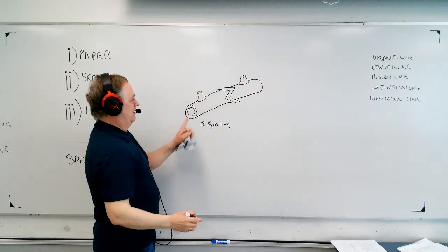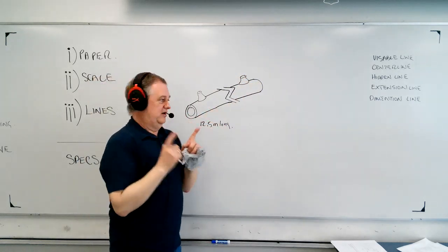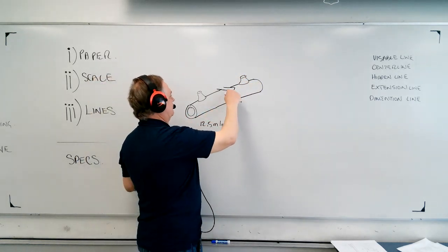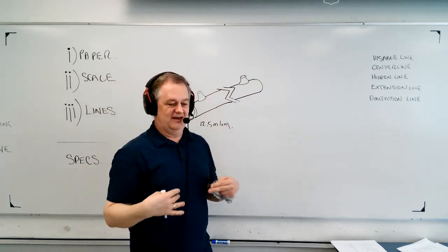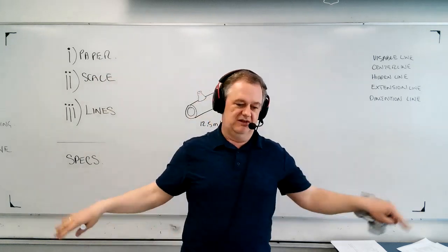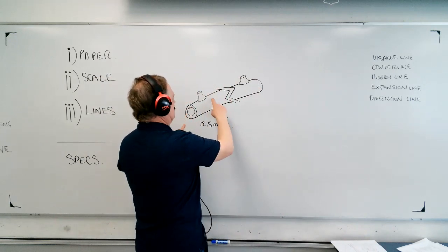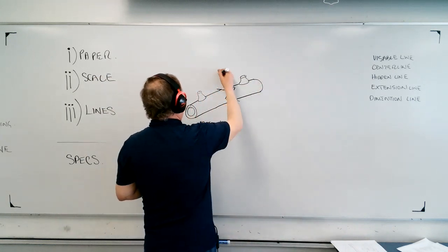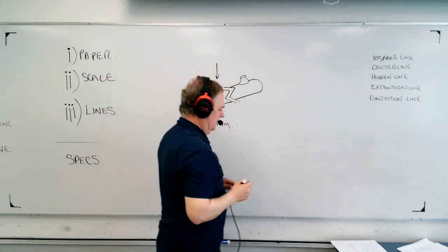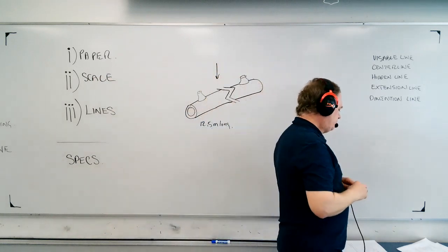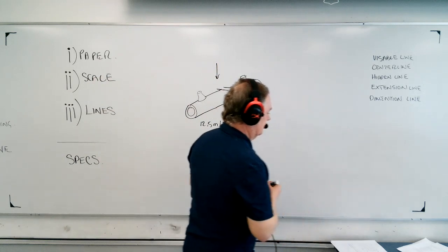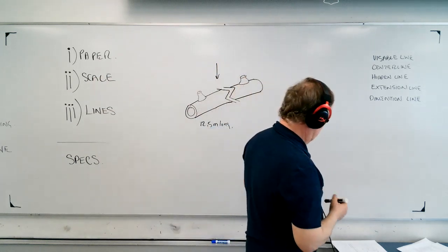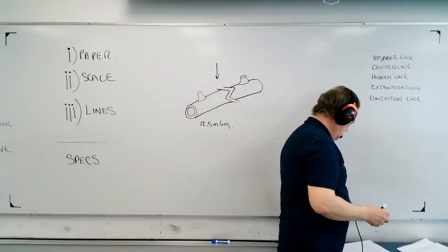Now on this drawing, they're like this far apart, but this line that's right here basically cuts out everything that is unnecessary because there's no change in the dimension of this from one end to the other. And so these lines that we have here, they call them basically short and long break lines.